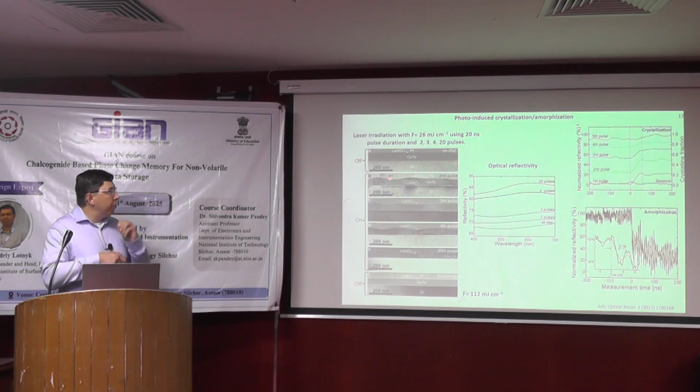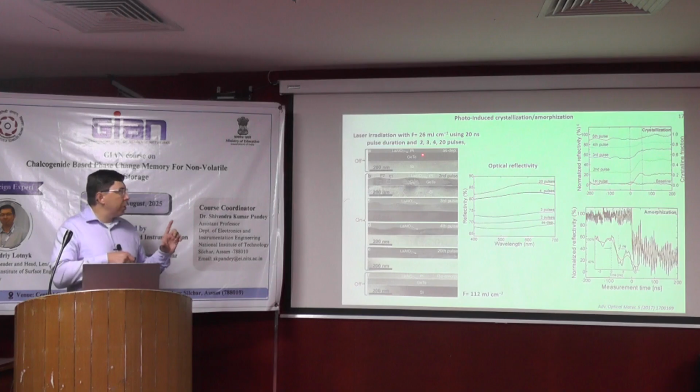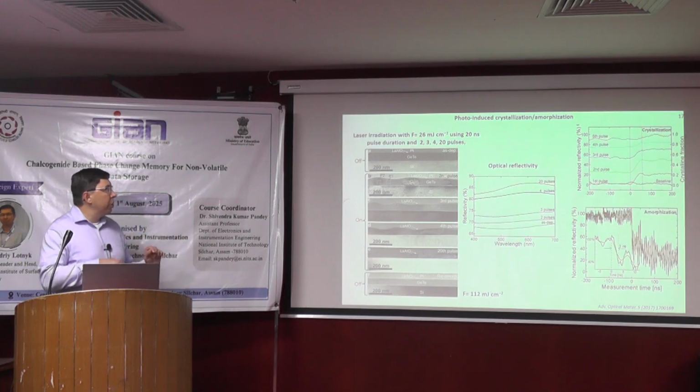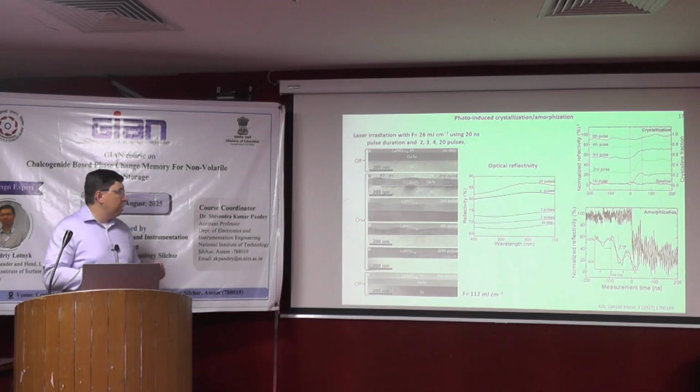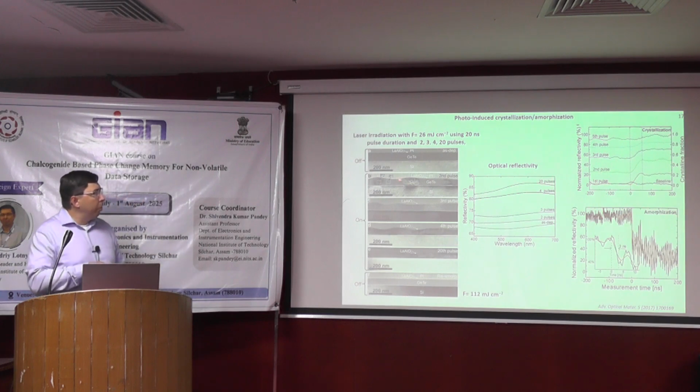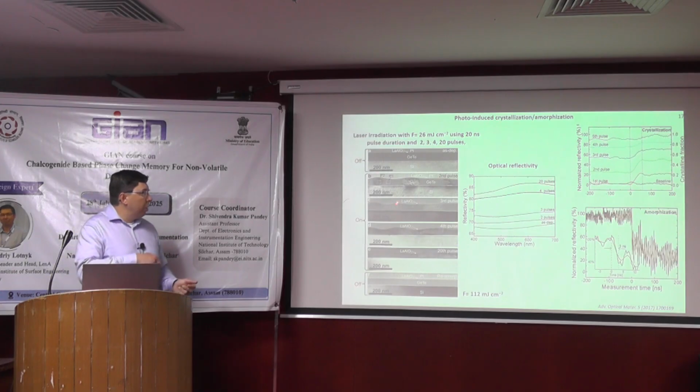Here you can recognize many problems with undoped phase change materials. First, there is a volume change up to 10% in the case of germanium telluride, and if it's changing, you can get a high roughness of your material. If you want to use it in a device, it's not good because of contacts. You can lose some contacts after several switching. So you maybe need to dope the material to reduce this roughness of the film.